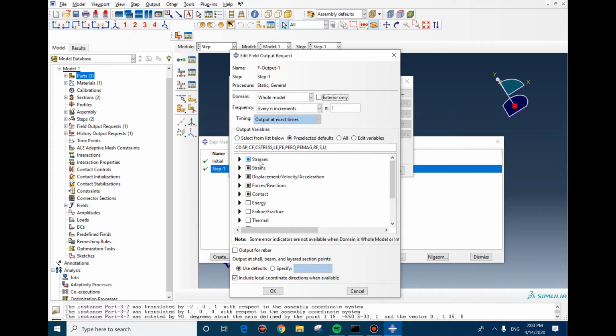But if you have a mechanical model, you will see this, and after solving the model you will have the residual stress and the stresses during the process. If you want to see this in your output file, you need to check this. If you don't check it, it doesn't mean it doesn't consider the stress. It calculates the stress, but it will not show it to you.